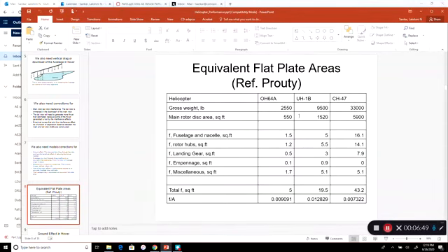Notice that many things are contributing to it. The fuselage is 1.5. The hub alone is costing 1.2. So the fuselage is a big thing. The hub is that little piece sticking out on top of the fuselage to which we are connecting the rotor. It can be very high drag. Notice that hub drag is contributing a significant amount.